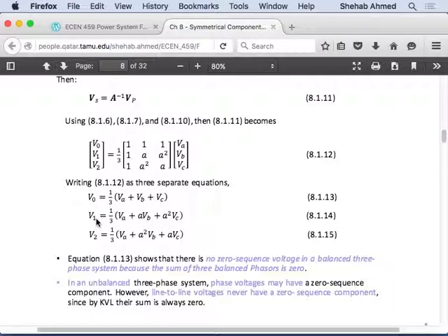You can have positive and 0, meaning your system has a lot of positive sequence, but there is some connection to ground. That means there is some current flowing in the neutral. But you can also have the same condition with negative sequence. So you can have negative sequence and zero sequence present. It means you have an unbalance.